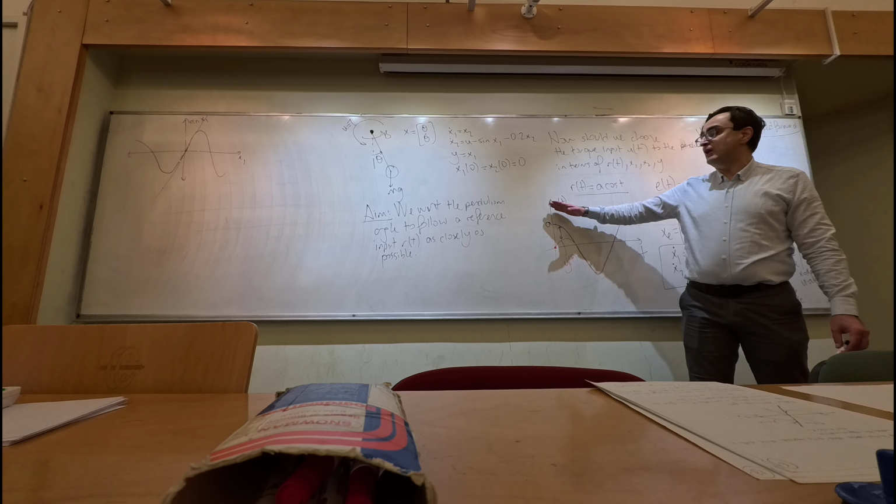But here the thing that we're going to do is that we will first design our controller. For designing our controller, I'm going to start from the output signal. We know that the output signal is equal to y is equal to x1. And our aim here is going to be to make the error signal go to 0. We will start from y is equal to x1, okay? And then I will start taking derivatives of y until the input appears on the right hand side. So let us take the derivative of y.